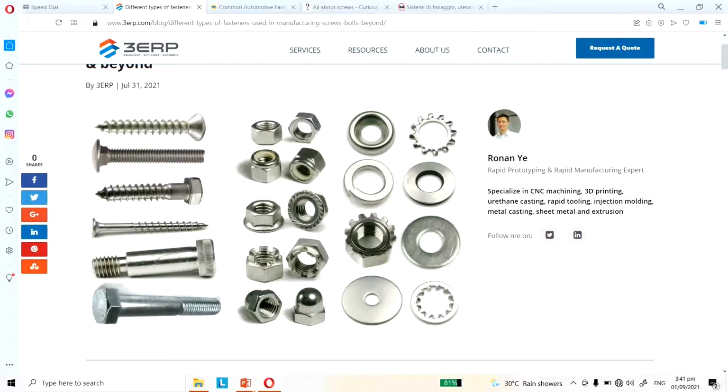And we also have a nut like this, I think this is a castellated nut. If you have a bolt or a pin, for example a bolt with a hole, the pin to be inserted in the hole will fit through these slots. So that's one of the applications of this type of nut.